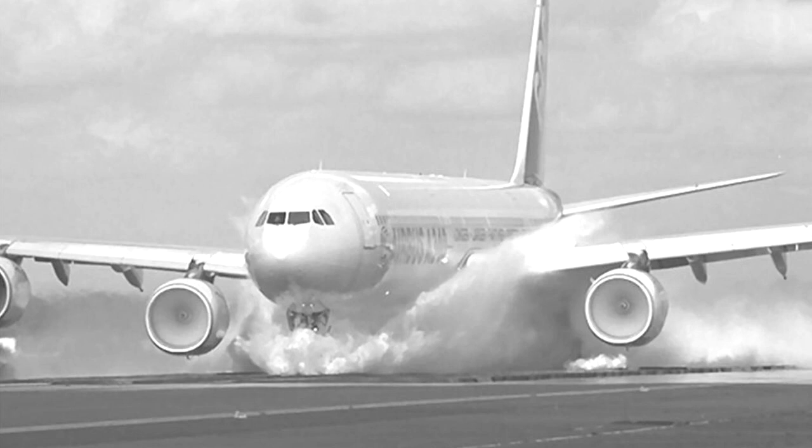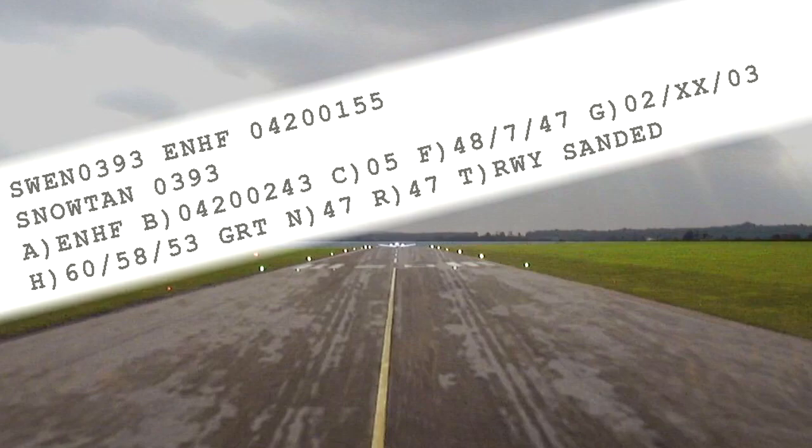The information on the runway contamination and braking effect can be given to the pilot through a report. These reports are either by SNOTAM, Runway State Code, PIREPS, or spoken by Air Traffic Control. These reports may include braking action or braking coefficient. Use any runway report together with your aeroplane flight manual and standard operating procedure to best gauge the landing technique and landing performance.